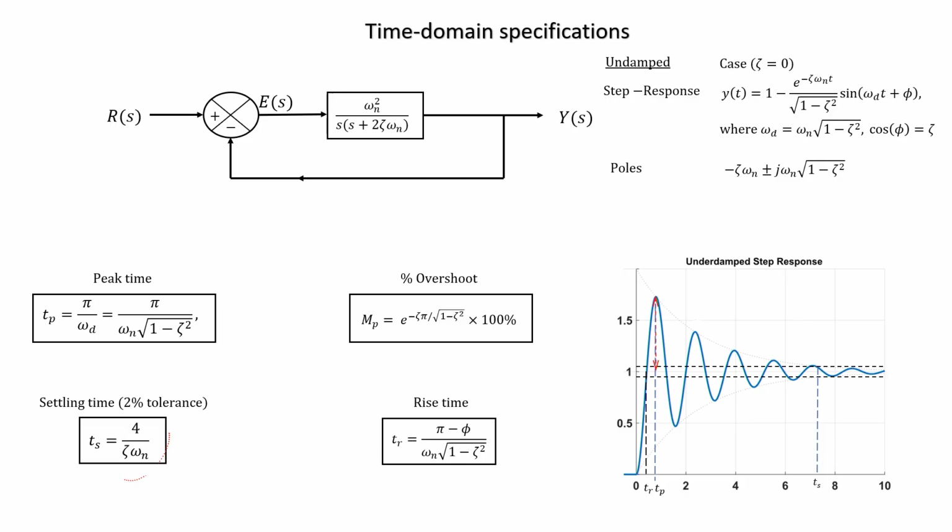But it might turn out that when you try to do that, your overshoot becomes very high. What is the problem with overshoot? See, the output we are checking, right? If the overshoot increases, that means the peak value of the output is too high. Now, if the peak value of output is too high, it might burn out the system also, who knows. So these specifications have conflicts within them also. You are the person, as control engineers, who will have to resolve those conflicts. That is your work. Okay.